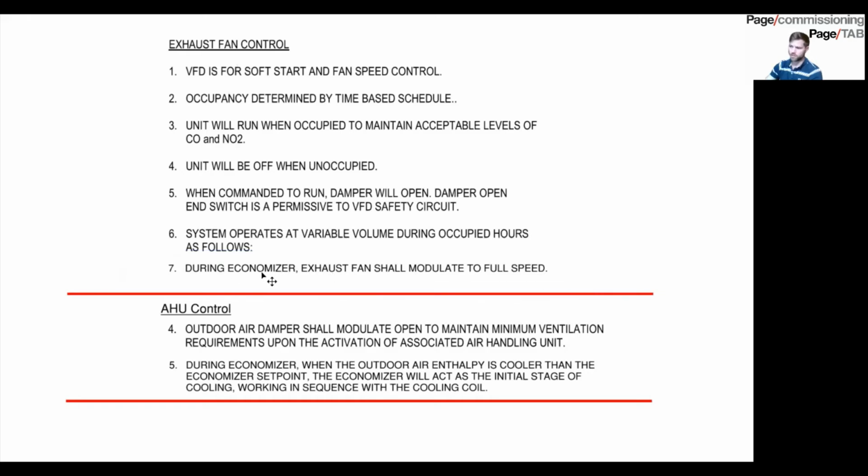Okay, so that means during the economizer that the AHU would go into, the exhaust fan is just going to go to full speed. Well, that could be an issue, right?